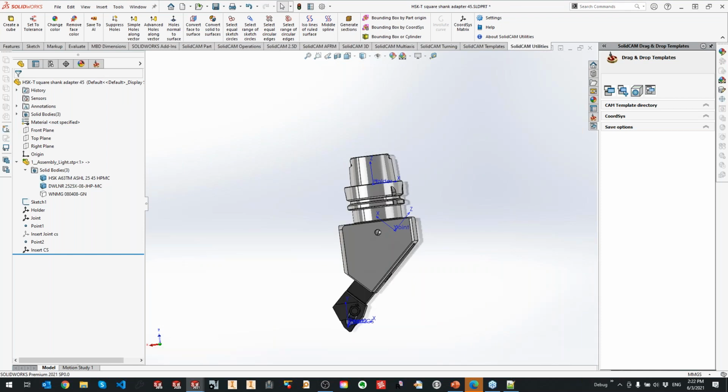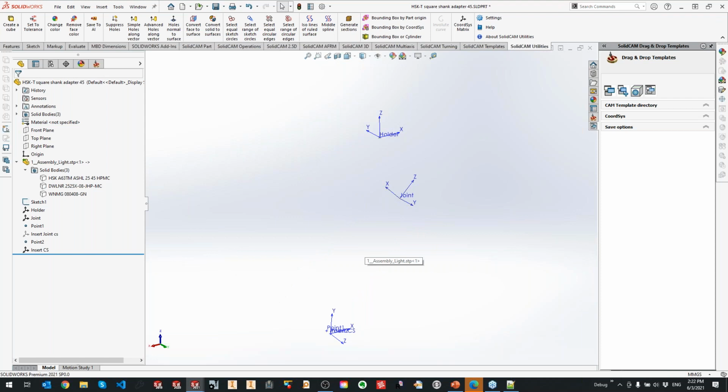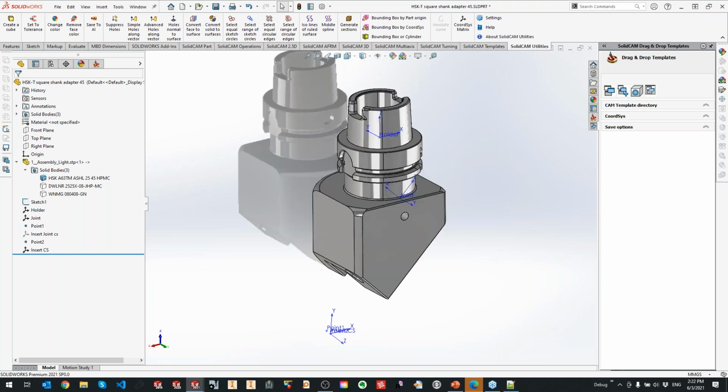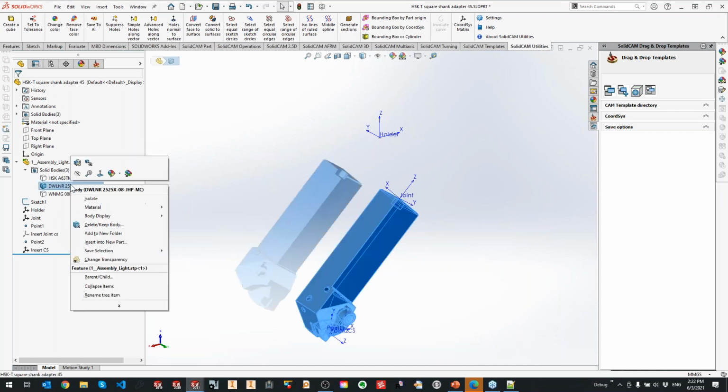Let's unhide the shank. By the way, for all of you, I see the question like how I'm hiding and unhiding. You can hide with a tab key, okay? But if you want to unhide it, you can leave your mouse wherever you are and just where you think your component is, you can do a shift tab, okay? So you can also unhide the component as well. Where is that? Yeah, so shank.